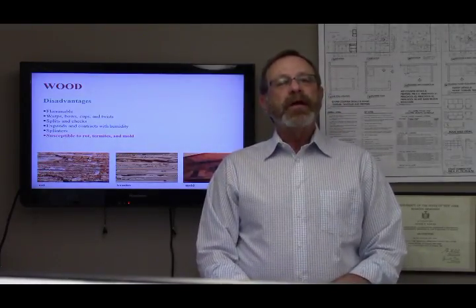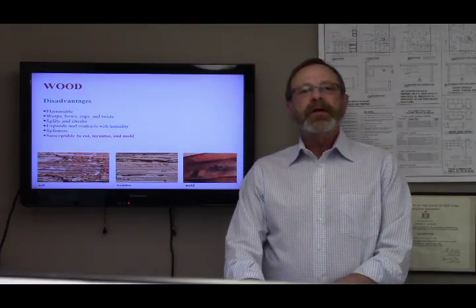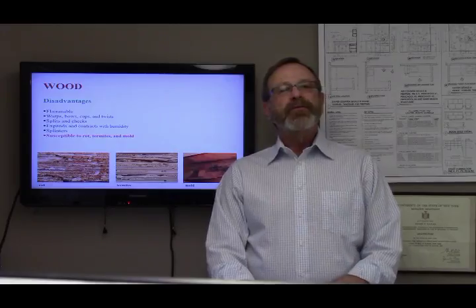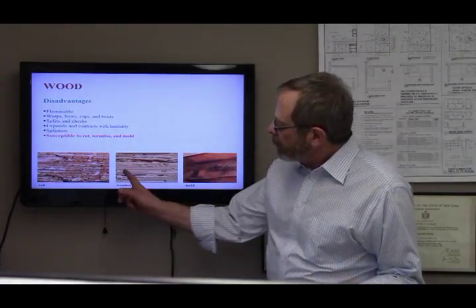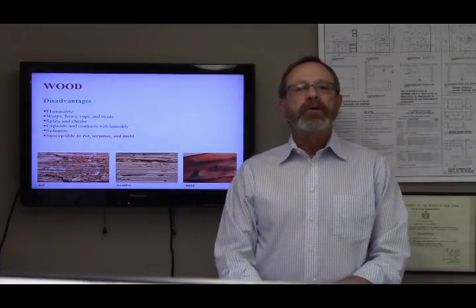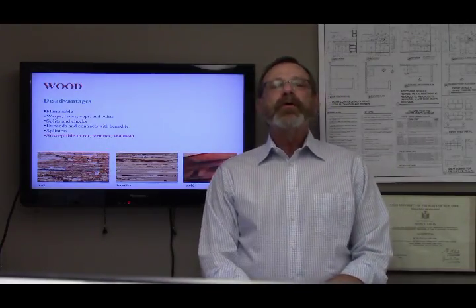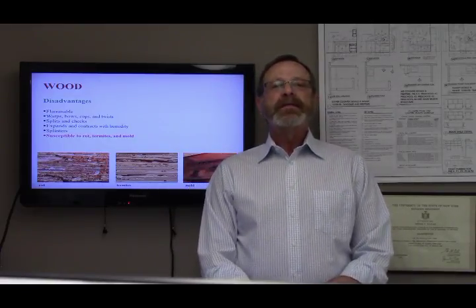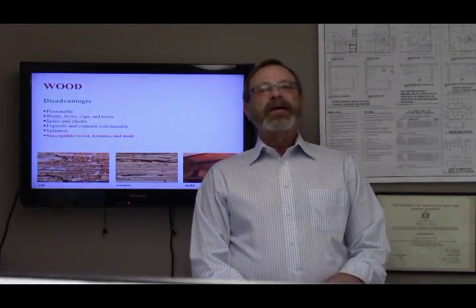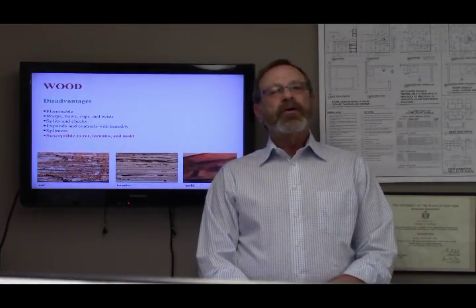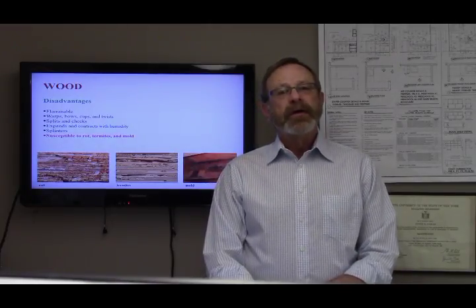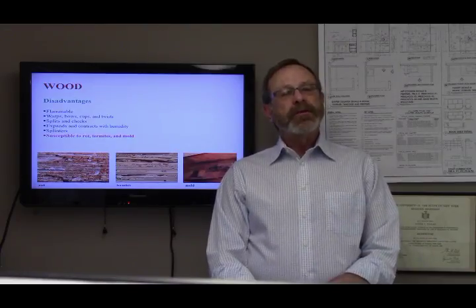Termites are a real threat to every homeowner. When these little insects are present, you will find hard mud trails running the length of the wood. Here are these little trails. To determine if the trails are new or old, break through the surface. If there are small winged insects inside with straight antennae, it is time to get out the termite treatment. If there are larger insects inside with double antennae and are a darker color, these are winged ants and must also be dealt with.